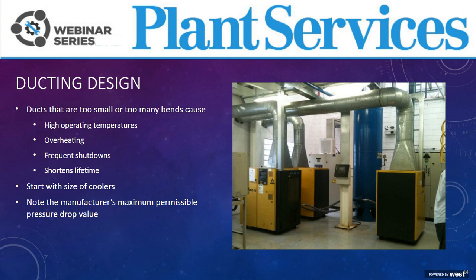The more complex the path of the ducting, with bends, elbows, adapters, etc., the larger the pressure loss as well. As you can see in this picture, you've got basically a cone that's going to a smaller space and then running out. So what that does is it restricts the flow and causes the machines to overheat.